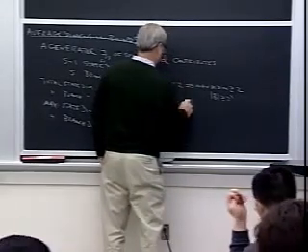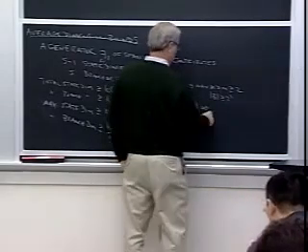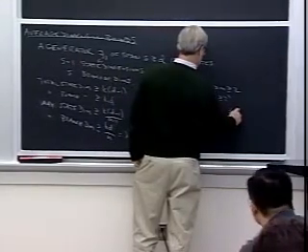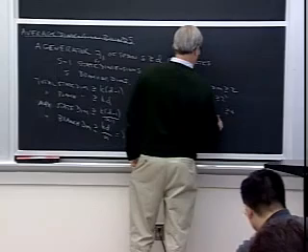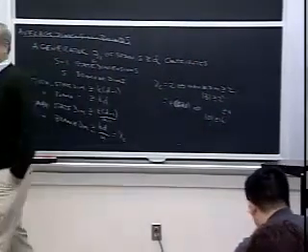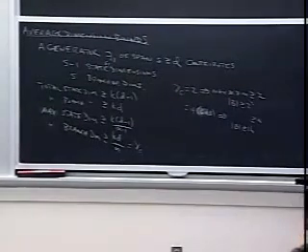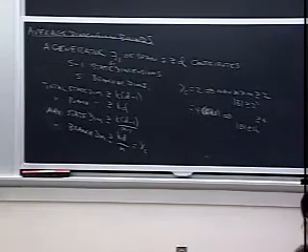let's just get right down to dB. It says you're going to need a branch space size greater than or equal to 4, or at least a 16 state trellis. So we know if we want a 6 dB coding gain, we're going to need at least a 16 state trellis, or 16 branch trellis. That might be an 8 state trellis.